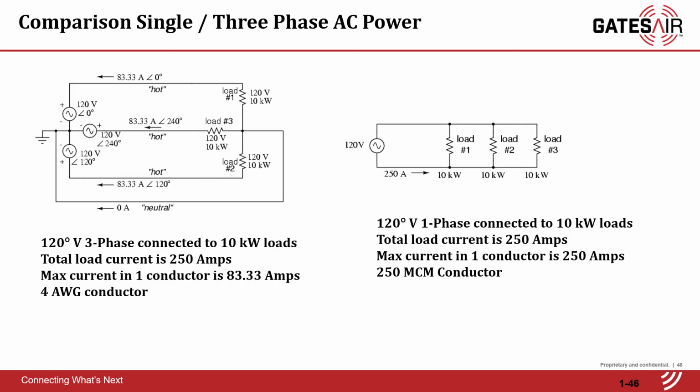Here's a quick comparison of a three-phase and a single-phase circuit with the same loads. Notice for three-phase, the current is much lower per leg than the single-phase. Thus, the wire for the single-phase would have to be much larger.